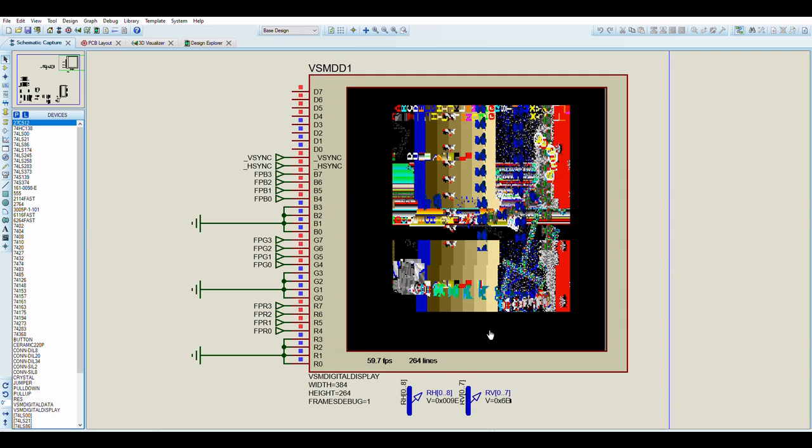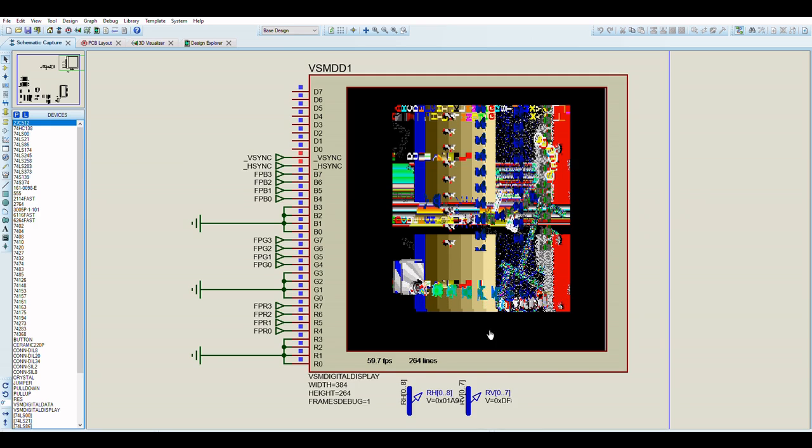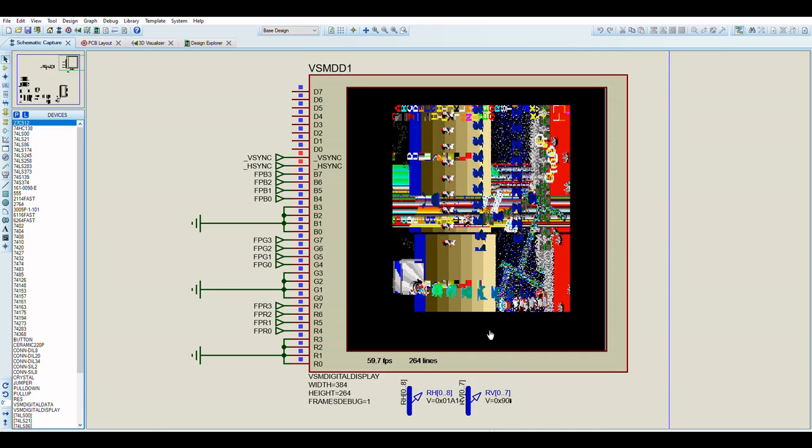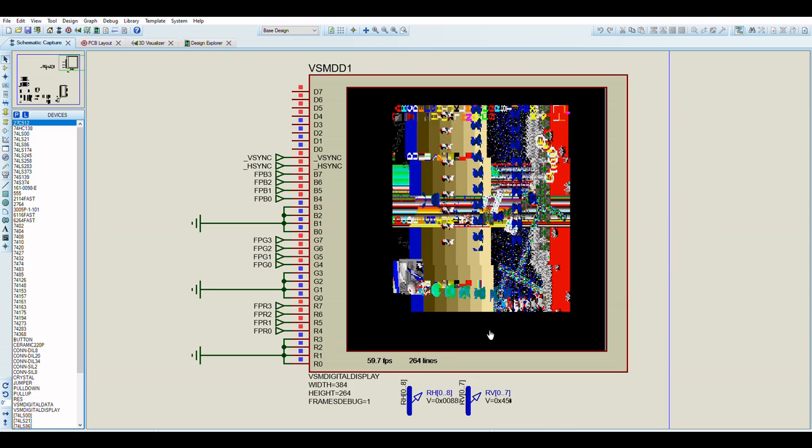The board worked, the video generation board worked first time when I was soldering it up and testing it. I think it's because I took a conservative route when constructing the board. I used sockets instead of soldering components directly to the board. I would solder the sockets and then put components in the sockets. All of the sockets for the ICs have decoupling capacitors, which helps with the board stability. It means that I do not need to populate capacitors on the board myself. It's part of the socket, which simplified construction in some way and simplified the board layout as well.